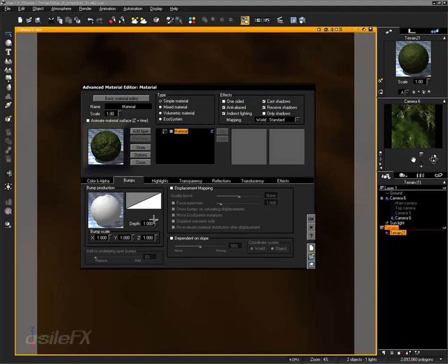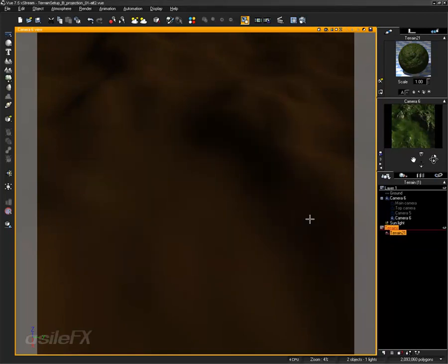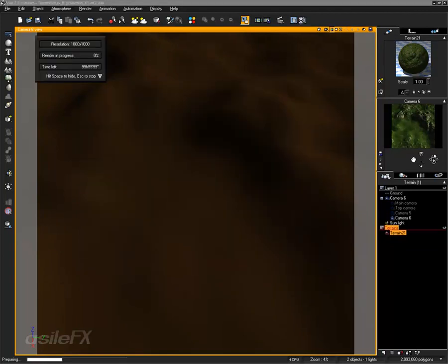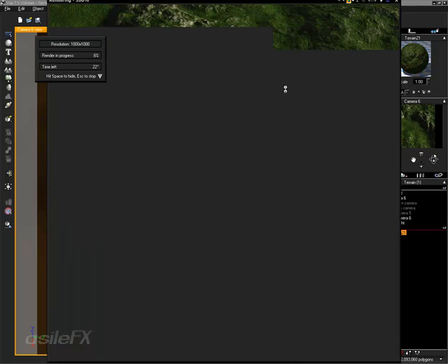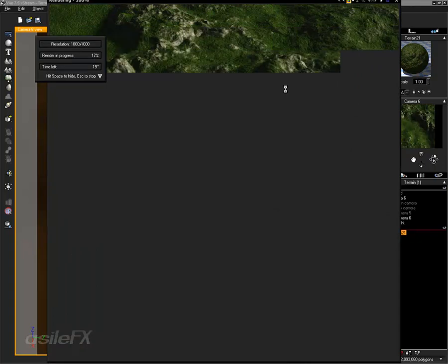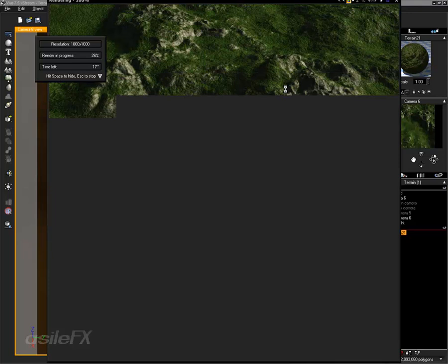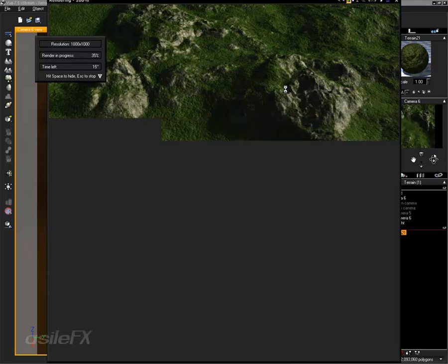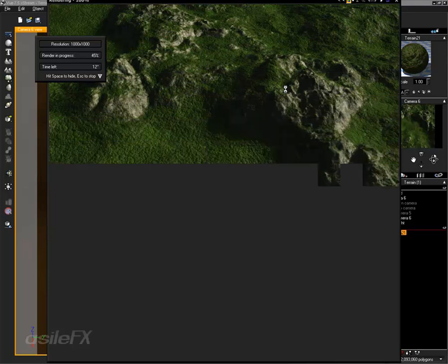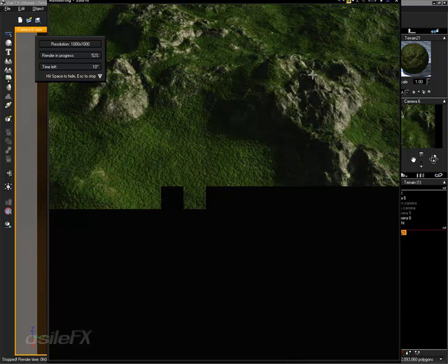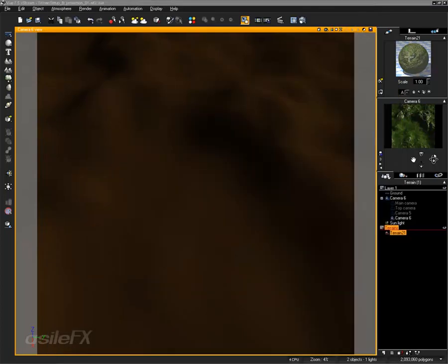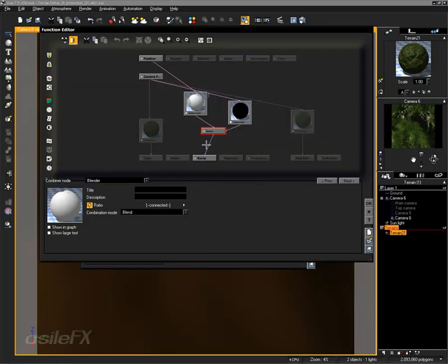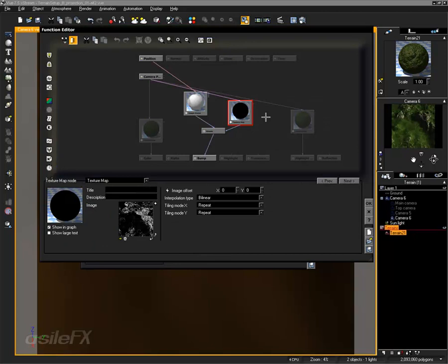And I had the bump set to 1 right now, which might be a little high. We could just go ahead and take a look. And I might need to invert the image, because right now it looks like it's affecting the grass, where I really want to affect the mountains more. So I'm going to go ahead and cancel that. What we can do is go back, edit the function, and just in the texture map, in the upper right of the preview, you can invert it.